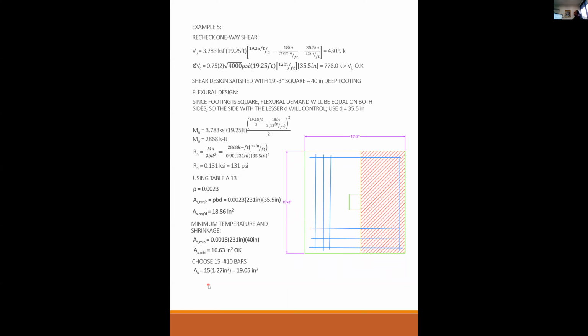Okay, but back to my question for the class. If As required is 18.86 and As provided is 19.05, am I done? Did I do my due diligence? Not yet. Why? You still need to check the phi Mn. That is right. That is absolutely right. That's what I was looking for.